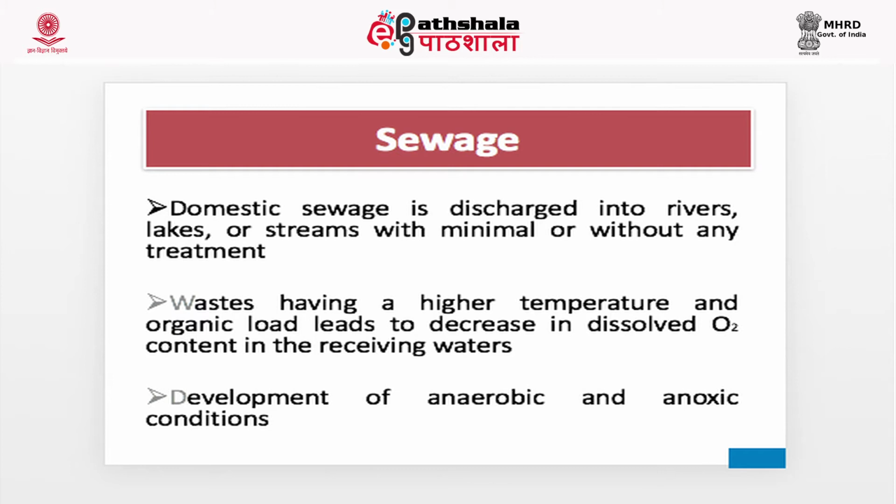Sewage. Domestic sewage is discharged into rivers, lakes or streams with minimal or without any treatment. These wastes, having a higher temperature and organic load, lead to a decrease in dissolved oxygen content, as do industrial effluents, and that dissolved oxygen content of receiving waters reduces and causes some anaerobic and anoxic conditions, resulting in sudden death